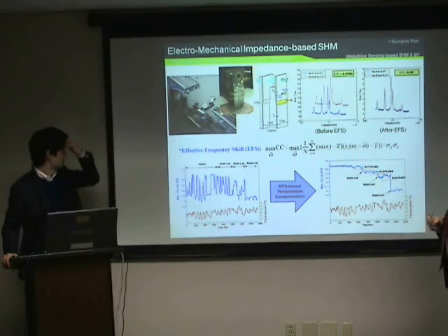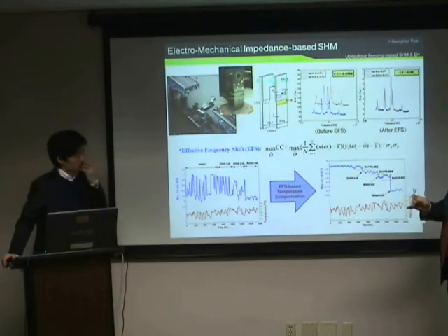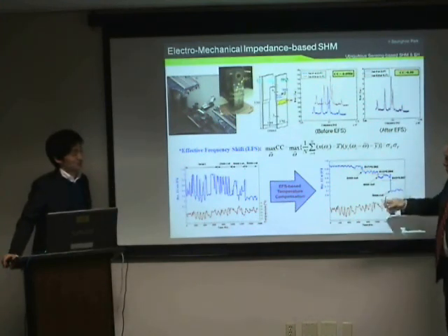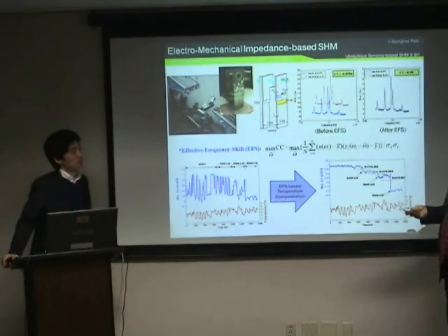I have a question about fatigue. Fatigue is usually a very slow evolving phenomenon. We characterize fatigue with a diagram we call the SN diagram, which usually relates the number of cycles with the amplitude of the cyclic stress. Typically fatigue for metals like cast iron or steel will go into the 10 to the power 6 cycles. So it's evolving gradually. The fatigue will develop cracks at a very, very slow rate. At some point it is going to evolve into a large crack, which will propagate suddenly. So we are dealing with something slow, and suddenly we have a quick acceleration, which triggers a rupture, usually a brittle rupture. So how can your system capture something which is evolving so slowly?